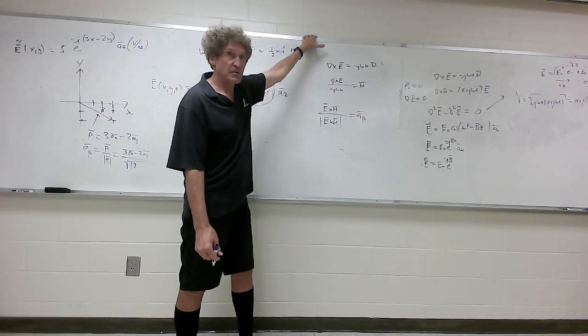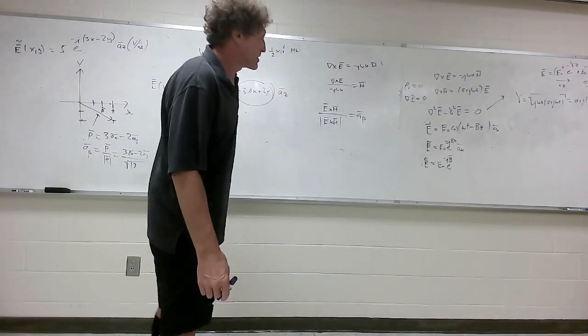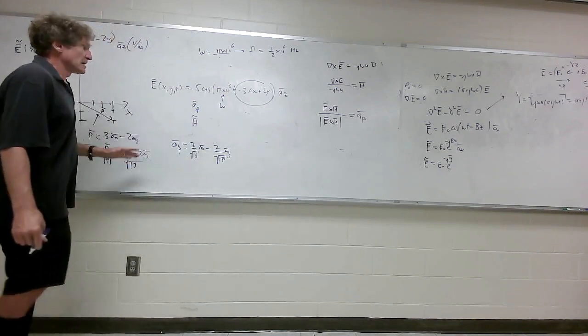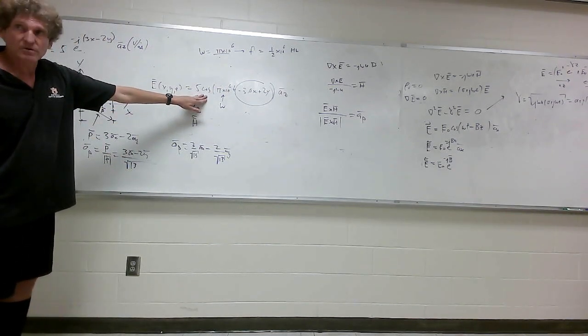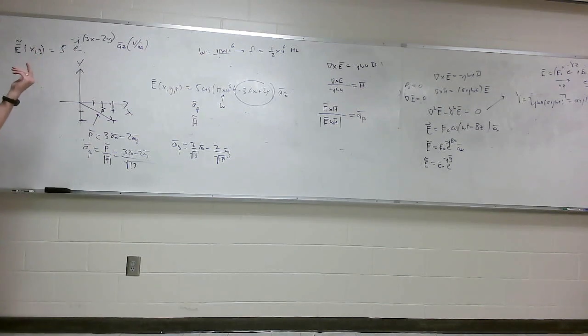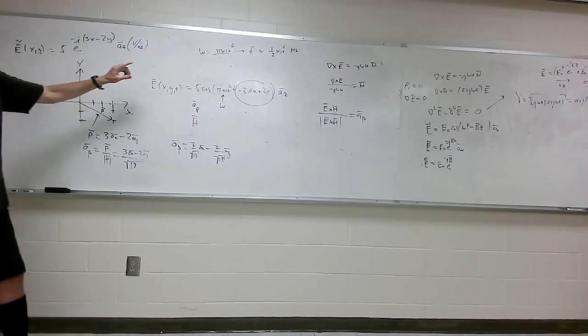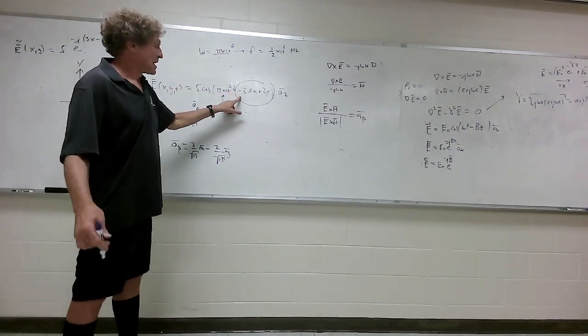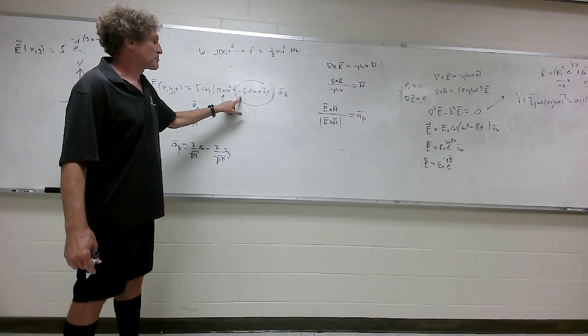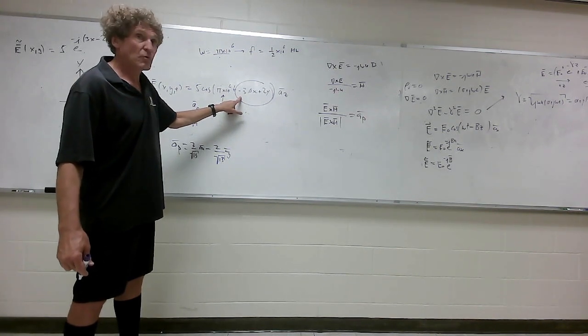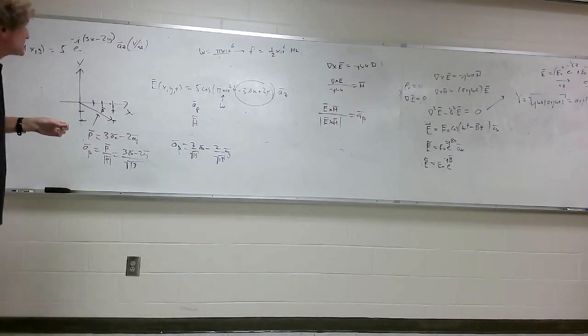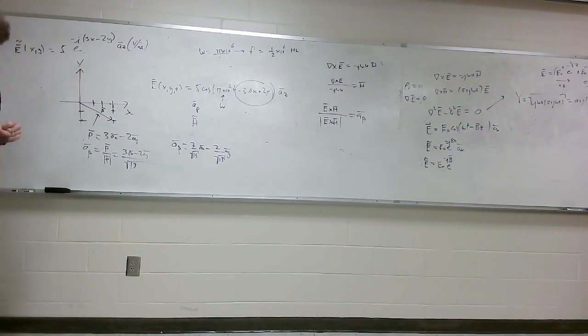The easiest way to get a unit vector in the direction of propagation, well, there's a couple of ways, but in my opinion, if you have something at constant frequency with a cosine form, put it in the phasor domain. That gets rid of the cosine of omega t variation. All right, so you have the magnitude, then it's e to the, you got to make sure you get a minus j there, right? Or pull the minus sign out there. And then you've got 3x minus 2y, and that will be enough information so you can simply let x and y be 1 and plot the vector p.